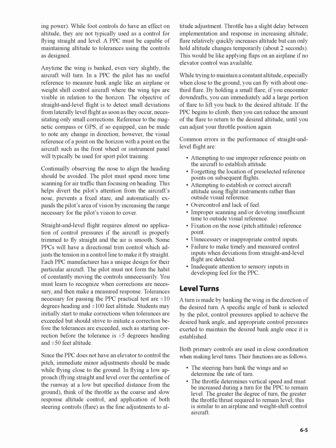Common errors in the performance of straight and level flight are attempting to use improper reference points on the aircraft to establish attitude. Forgetting the location of preselected reference points on subsequent flights. Attempting to establish or correct aircraft attitude using flight instruments rather than outside visual reference. Over-control and lack of feel. Improper scanning and/or devoting insufficient time to outside visual reference.